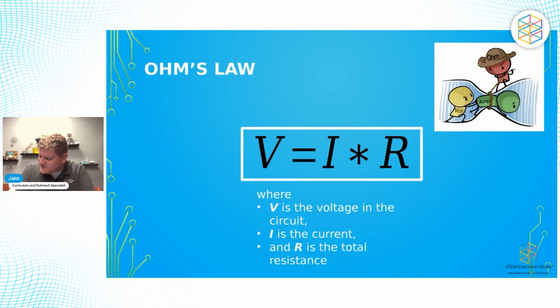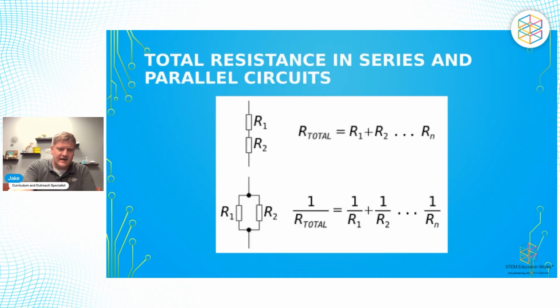But let's say that you're specifically looking at one single resistor inside of your circuit. If we know the total voltage drop across that resistor, and we know what the resistance of that particular resistor is, we can tell the exact amount of current flowing through that part of the circuit. So not only can Ohm's law be applied on the large scale for an entire circuit, but it can also be applied to specific components. Depending on what you're interested in, you may look at the full circuit, or just a small component of it that you can use Ohm's law to analyze.